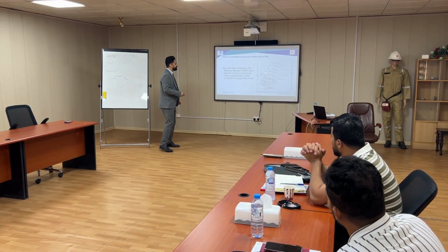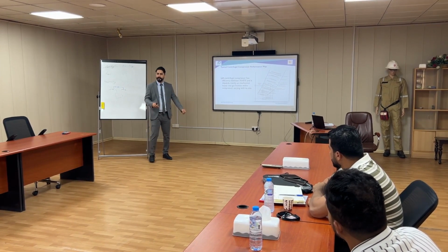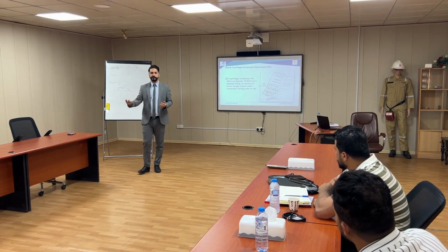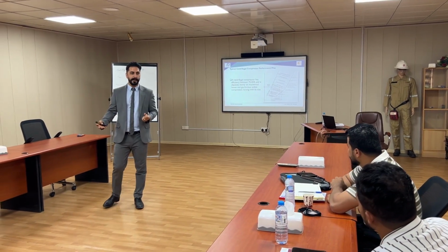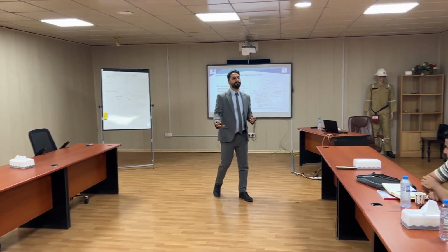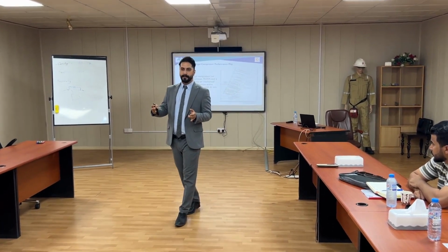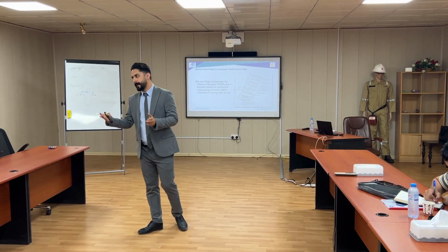The vertical axis of this curve is head. Head is actually the compression ratio, how much pressure can be produced by this type of compressor. And the horizontal axis is about the capacity. Sometimes we can see that some manufacturers of compressors release this type of performance curve, and the